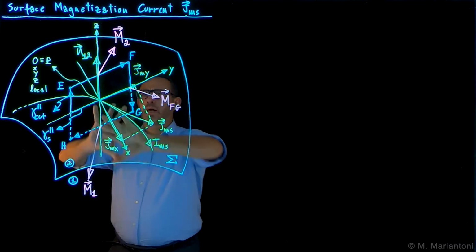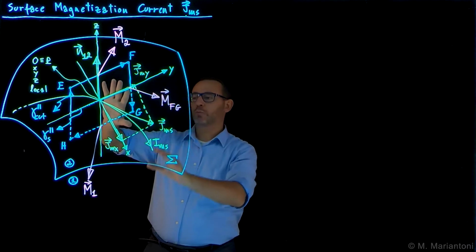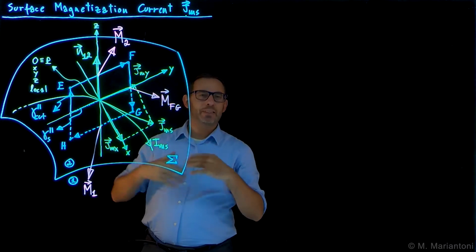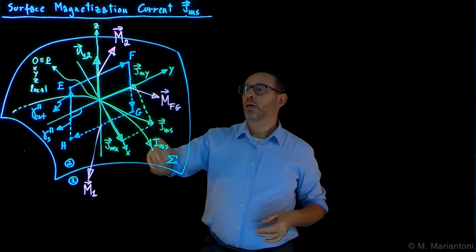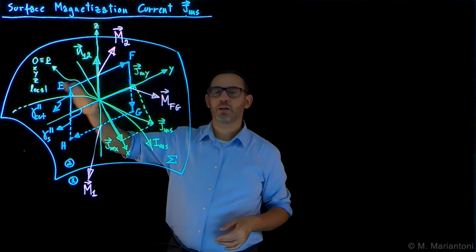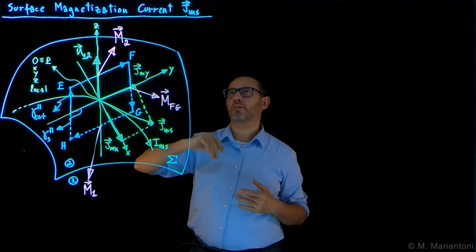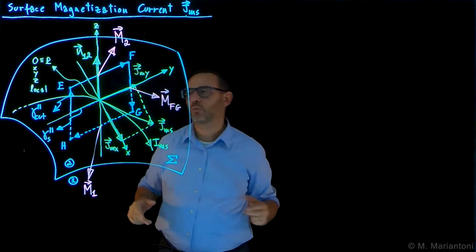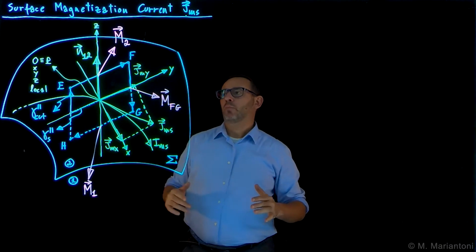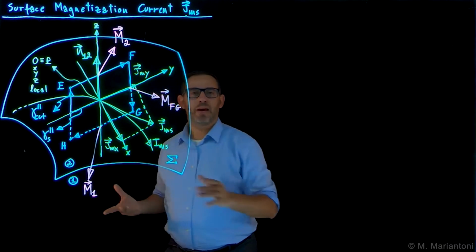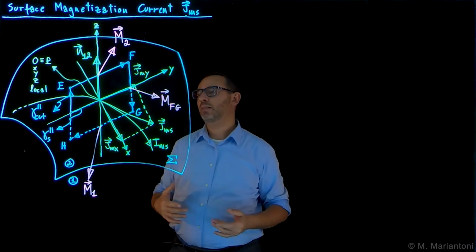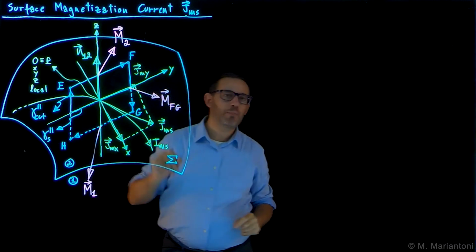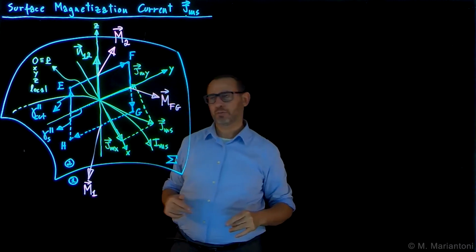Okay, so now we have a surface, which is the interface between two materials in region 1 and region 2. Let's say two different magnetic materials. This surface is a discontinuity, so typically we will have JMS. Well, we will have a current IMS, which is a magnetization current on the surface between these two materials, on this interface, which will be characterized tangentially, point by point, by a JMS, okay? Because they are stationary, so we can still do that. Now, we pick a point on this surface, there is a JMS at that point, and there will be a magnetization field M1 and M2 in the two regions, which now we want to squeeze down to study this M1 and M2 in the neighborhood of this point, capital P, which is at the interface between the two regions.